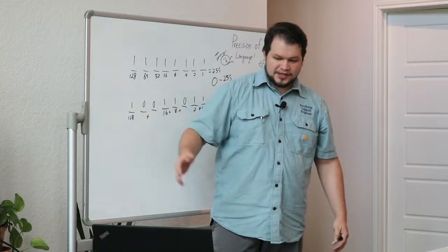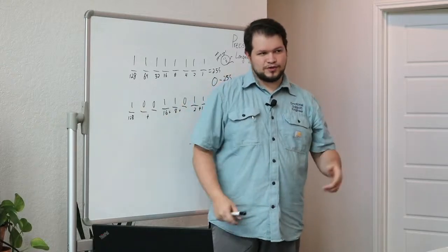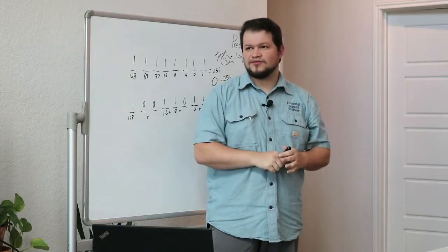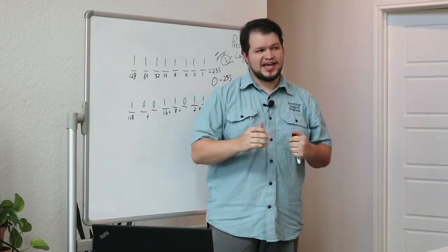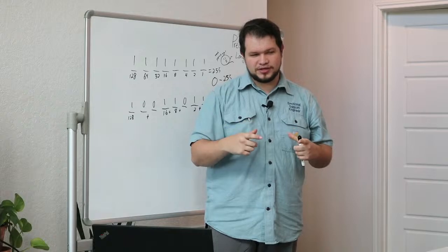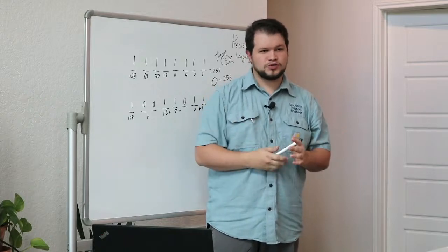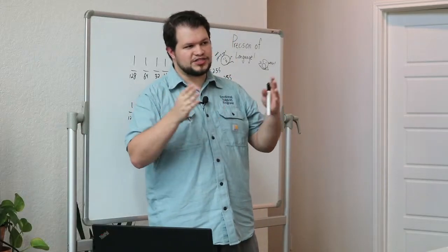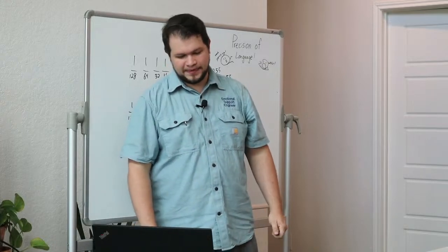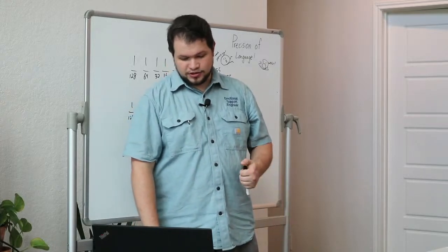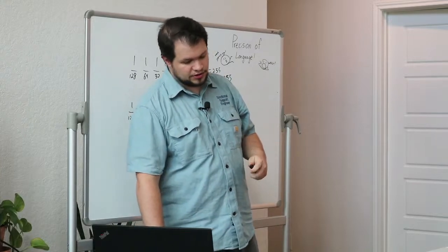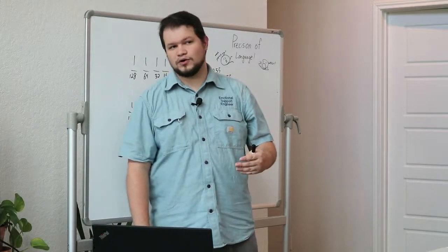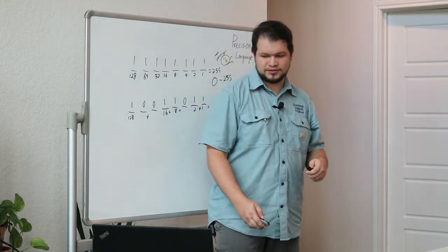The more numbers in your range, so an analog signal can be anywhere in that range, with the max value typically being that high number, the more bits you have in your range will give you finer points of accuracy. So when you have an accuracy listed on the component's spec sheet of like plus or minus 1 millimeter for a distance sensor, that has to do with how much information it is able to output in its range. Potentiometers and distance sensors are typically going to be analog, but encoders are fairly similar to potentiometers, and odometry is effectively encoders. So a lot of your signals will actually be analog signals.